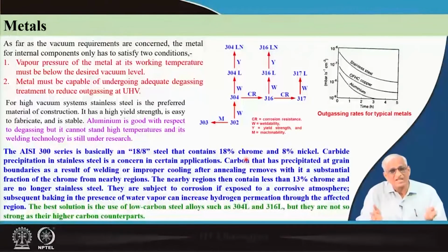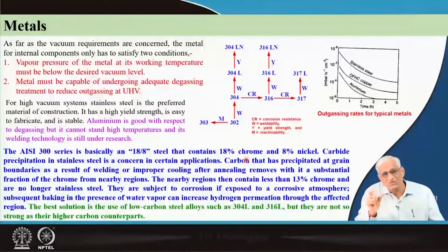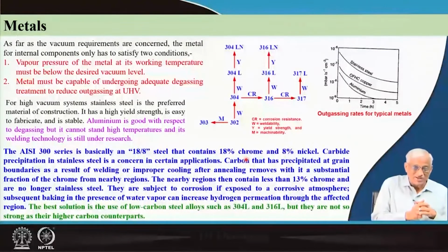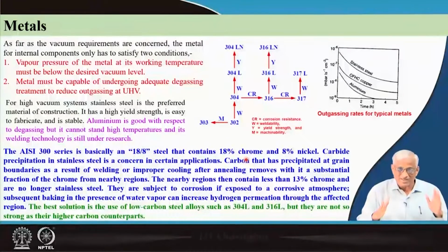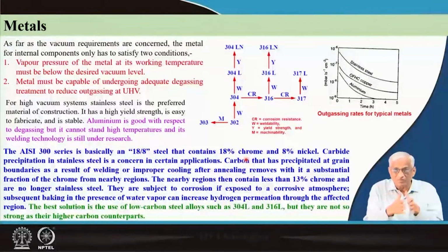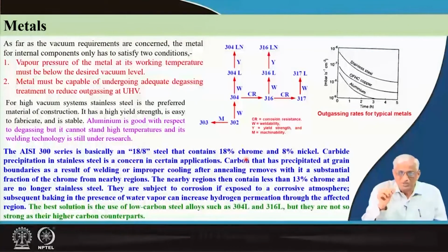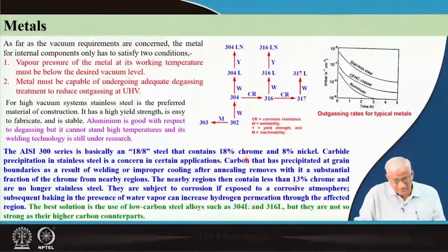Pressurized chambers inside can be 10 bar, 20 bar, 30 bar. So, delta P can be variable, but in vacuum systems once you cross 1 torr, delta P is only 1 bar, it will not change. But it does not mean that it is a small force from the outside, because the mechanism is elastic instability. So, it will collapse, that is dangerous. You should have some reasonable thickness. This thickness calculations we will see in the next class later.